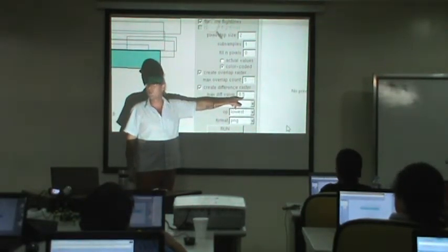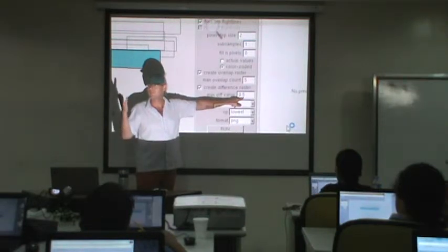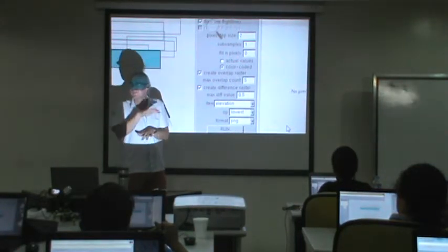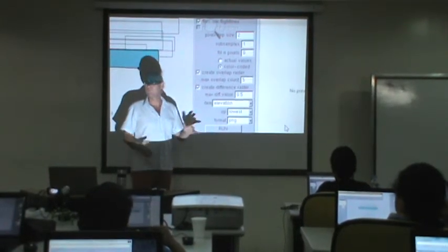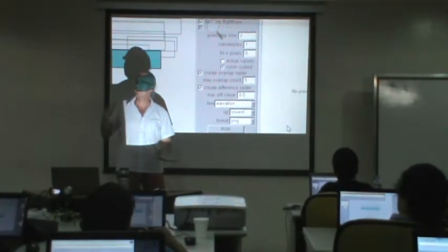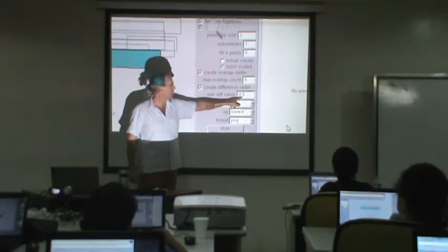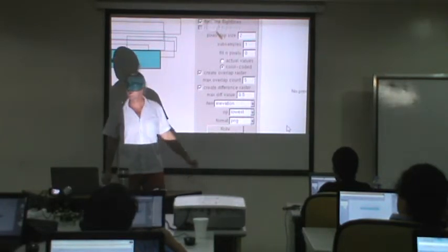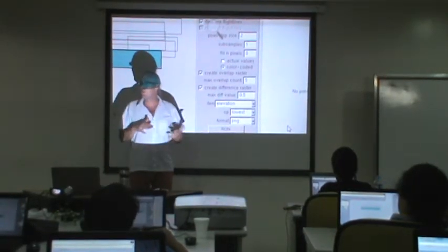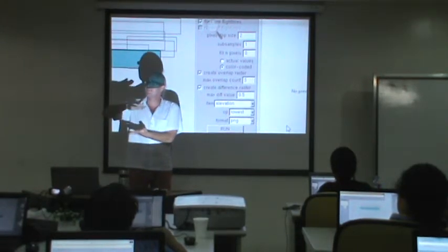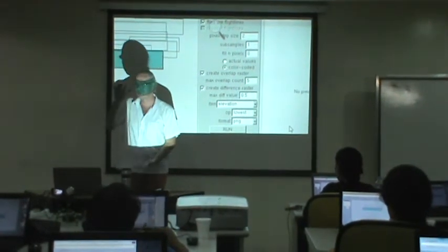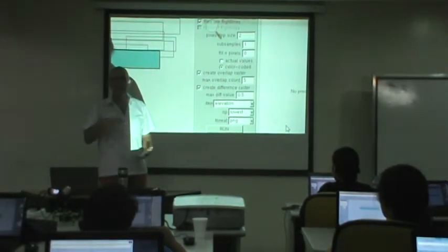And if this difference is more than half a meter, it becomes dark red. If it's a negative difference, meaning sometimes the flight lines are on top of each other in the other direction, it's blue. Blue to red. Both are bad. One is negative bad, one is positive bad. And this specifies when you want to turn them red. If I make this value small, like 0.2, then if I have a 20 centimeter difference, it will already be red. If I make it bigger, like 1 meter, then I'm visualizing only very big differences.